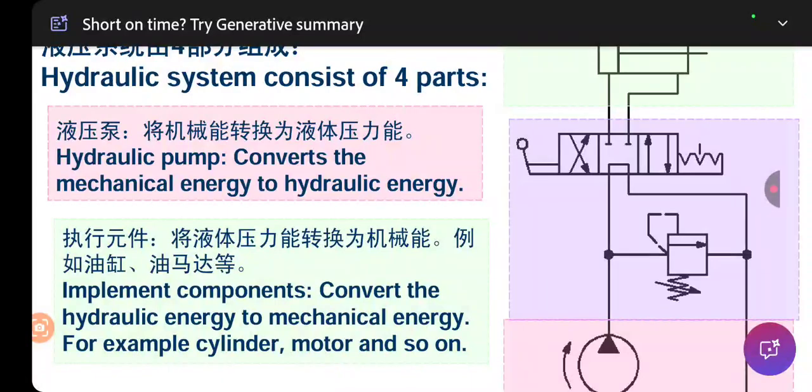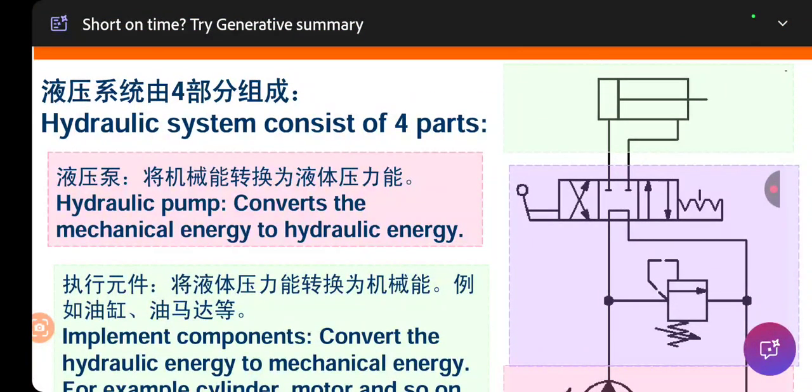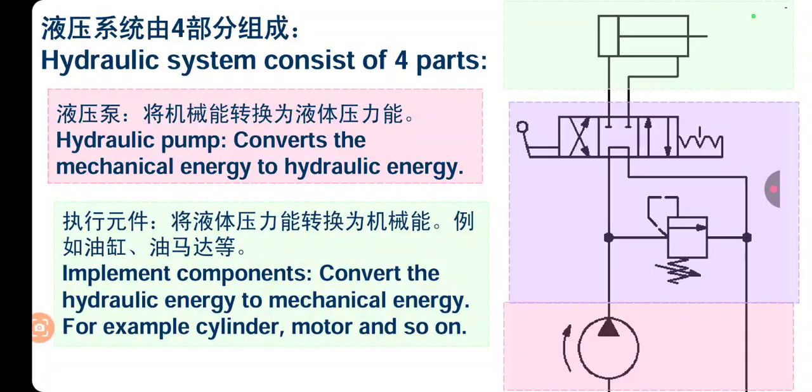And relief valve. What is relief valve? A relief valve is a device which relieves the extra pressure towards the reservoir or tank. Okay. In this condition, it is fitted in between the control valve assembly and the pump. It's fitted between pump and control valve. Once the pressure exceeds the limit, then it will be released towards the tank. Okay, so this is the relief valve.